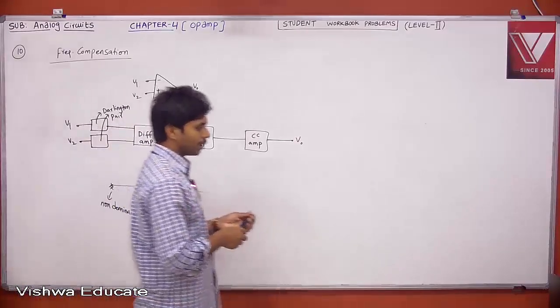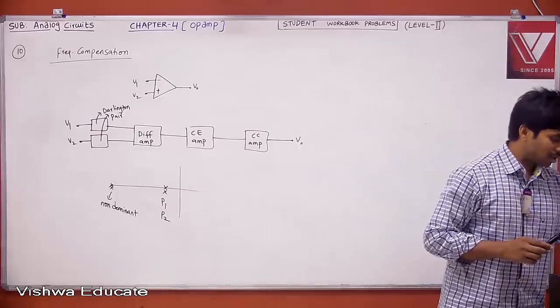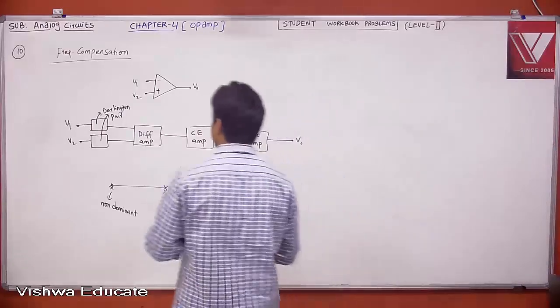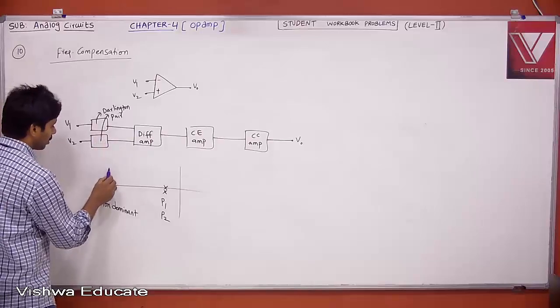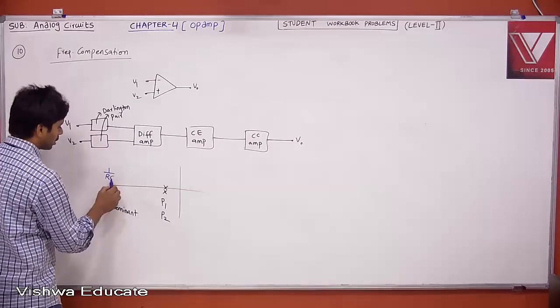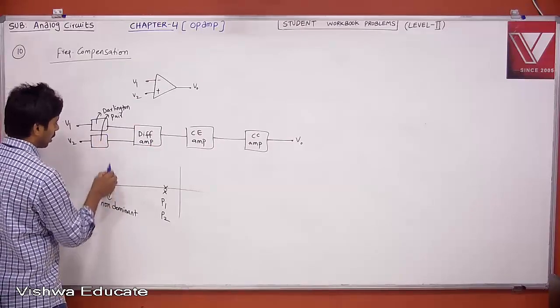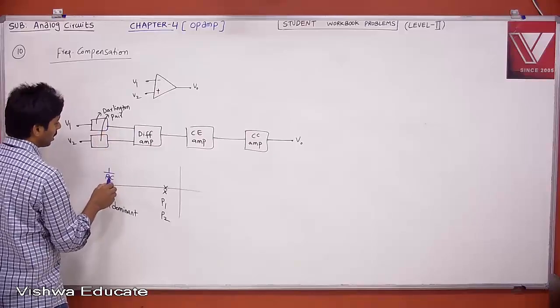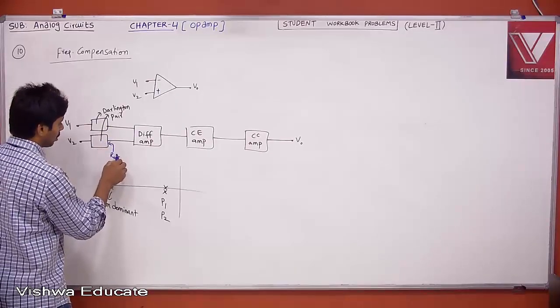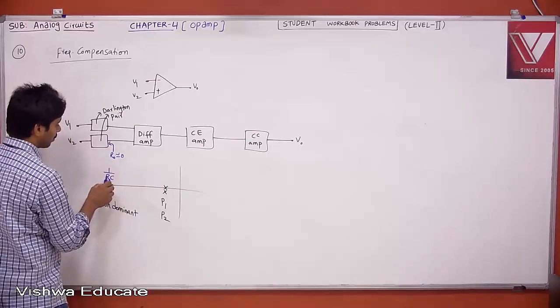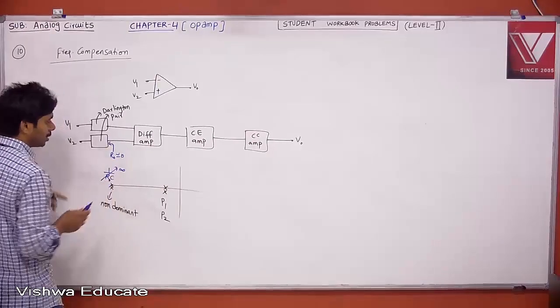Because everything has output resistance and output capacitance. The output impedance of your Darlington pair is very low. Whatever poles you have are from R and C, with R0 and the load, but R0 is almost 0. When this is 0, this pole is at almost infinity.